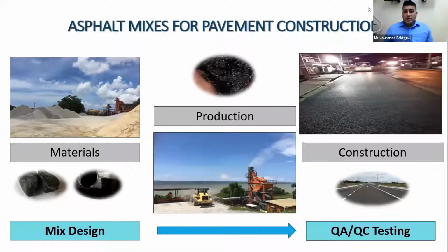When we look at the different stages in the asphalt mix design process, manufacture, and construction, it is evident that material design requires laboratory analysis. There needs to be quality control and monitoring throughout the entire process. On commencement with the mix design, the laboratory analysis should encompass determining the material characteristics and their suitability for use. These characteristics include grading, shape, geometry, durability, and strength.